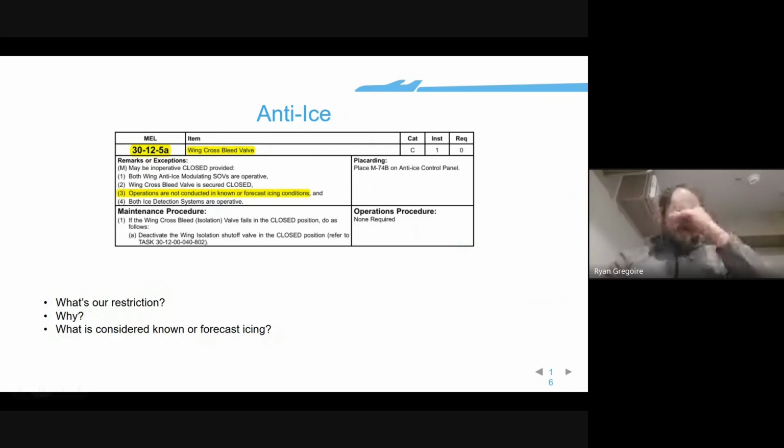And in my current role, I sit right next to maintenance control, and they will always turn to ask me, "Hey, could we dispatch this plane no icing?" And I mean, in the winter, it's almost always no, though. Really, we can get around it a little bit easier in the winter because it's a lot more cut and dry where icing conditions are and are not. Basically, in the winter, if you can avoid clouds, you can avoid icing conditions.